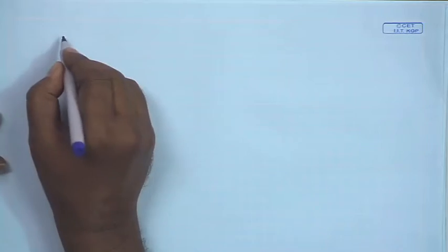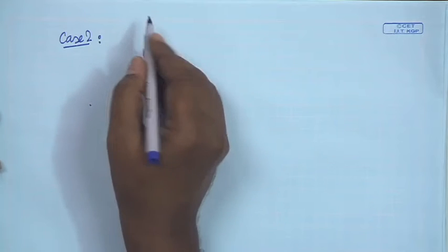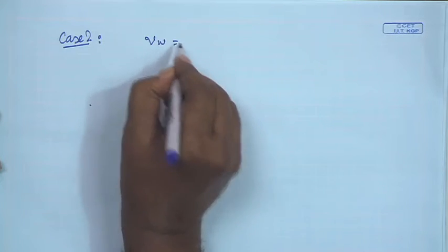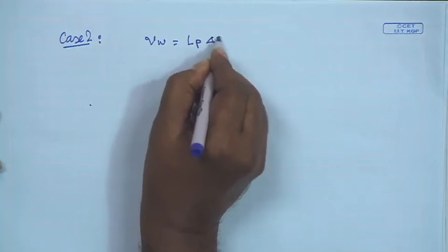In the third and final analysis, case number 3, osmotic pressure is not at all negligible, and we will be doing a real modeling of the membrane module. So, in this case 2, we will be considering that the permeate flux is proportional to the transmembrane pressure drop.